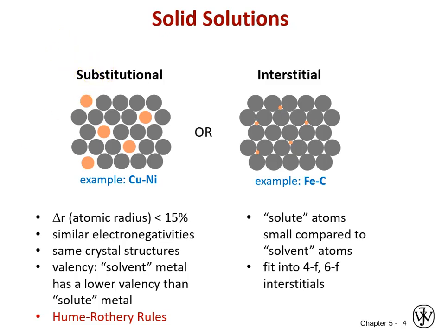So in addition to having vacancies in a pure material or having a self-interstitial in a pure material, we can start now mixing different elements, different materials within one another. And this will give us a solid solution. You're probably really familiar with other types of solutions in liquids and gases because we encounter them all the time in everyday life. In fact, you're breathing a gaseous solution now, air being composed of nitrogen and oxygen in a solution. Salt water, sugar and water are very typical liquid solutions.